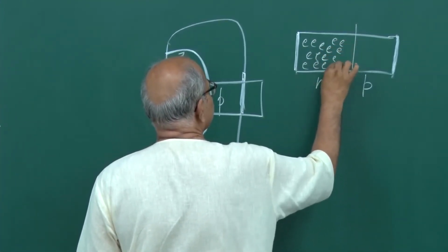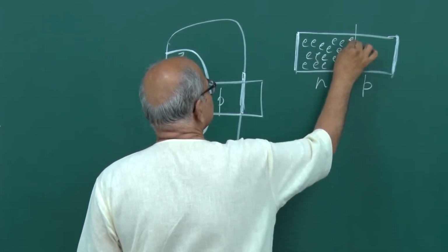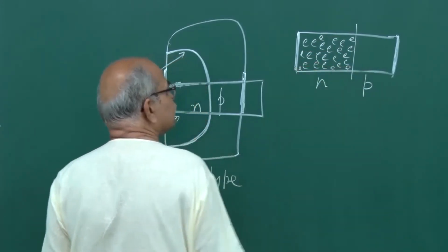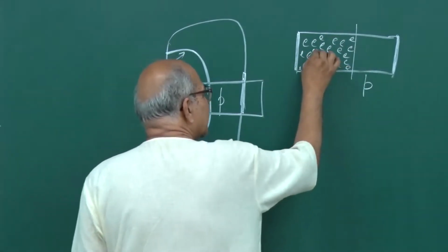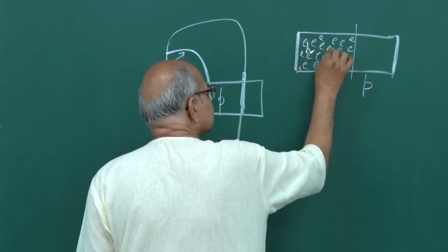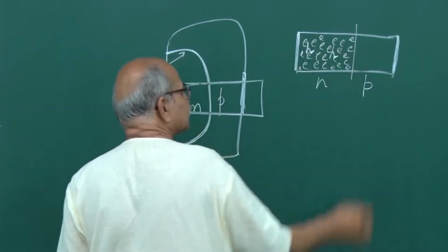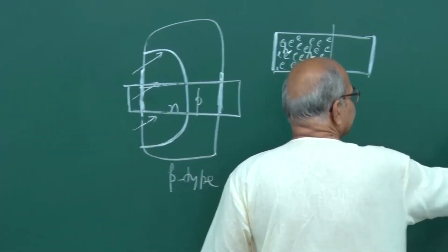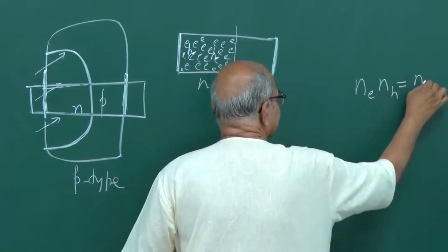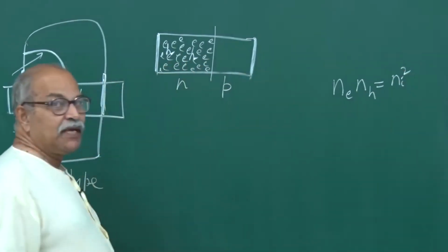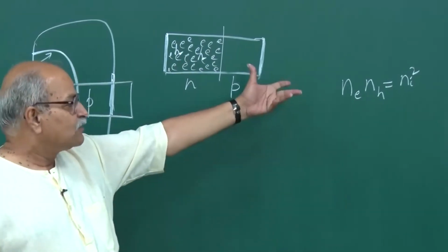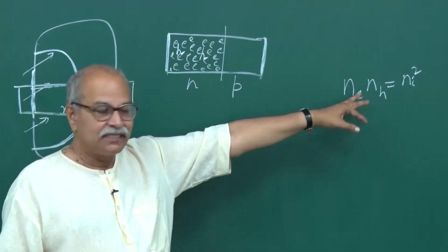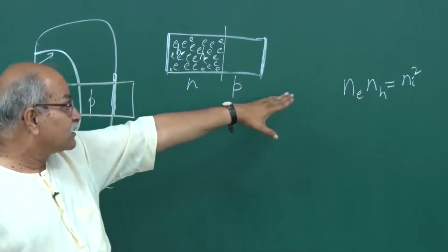Because of those pentavalent impurities, you have a large number of free electrons here, and you have some holes here in between. Small amount. Remember, n_e times n_h is fixed, n_i squared. And for ppm type doping, we had calculated that the number of holes reduces to a few thousands per centimeter cube, but they are still there.